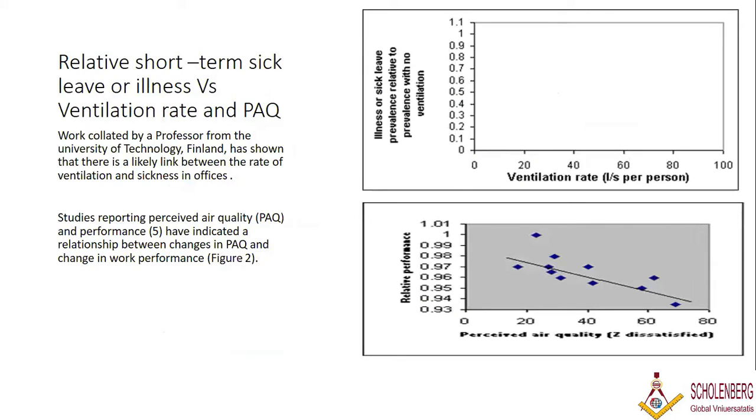In fact, there is a National Association of Duct Cleaning, and they came out with very good standards about 10 or 15 years ago. They strongly recommend that every 3 to 4 years the entire ducting system should be cleaned, by sending robotic cameras to see the condition of the ducts. I will show some diagrams. Duct cleaning is now another important business activity in the majority of hospital areas, and in some countries it has become a statutory requirement that the duct be cleaned once every 3 to 4 years.